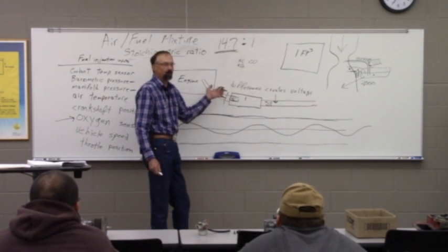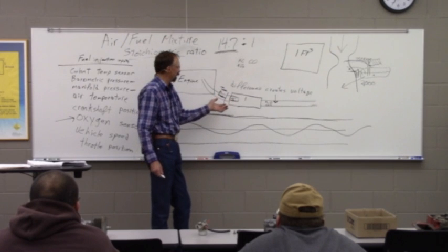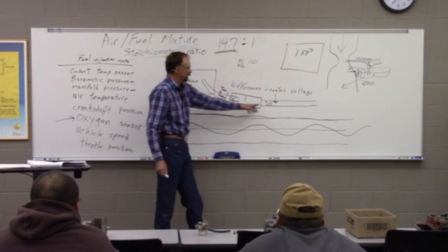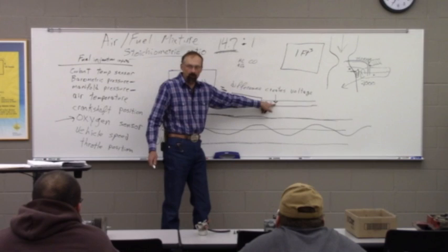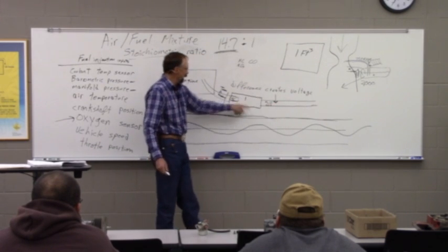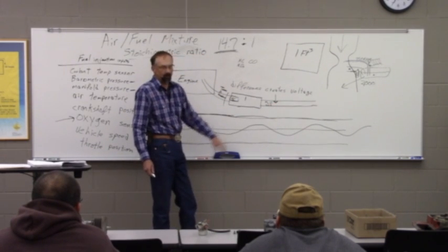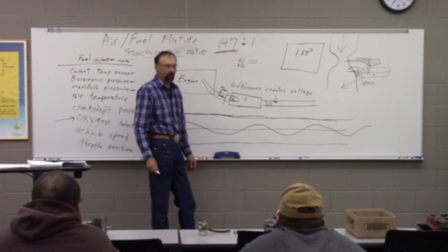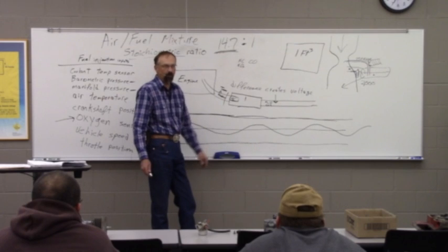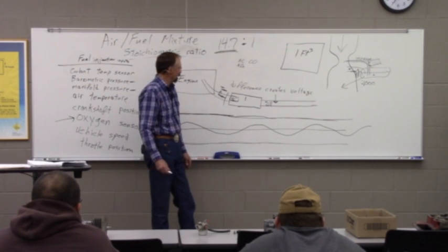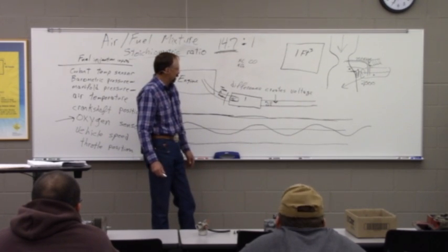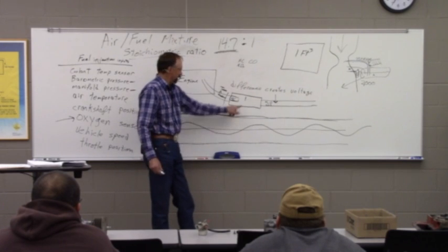But as far as how the pickup ran, there were no ill effects. On any of the vehicles that have the downstream O2 sensor, if you cut that cat out, it's going to nearly immediately turn on the check engine light for a catalyst efficiency code or a downstream O2 efficiency code. And to get that annoying light shut off, you're going to have to have the cat.